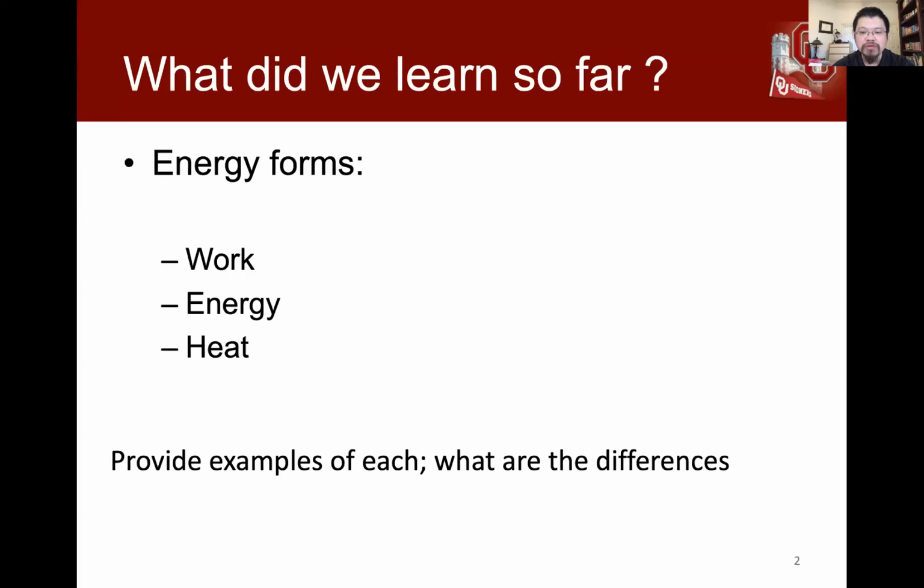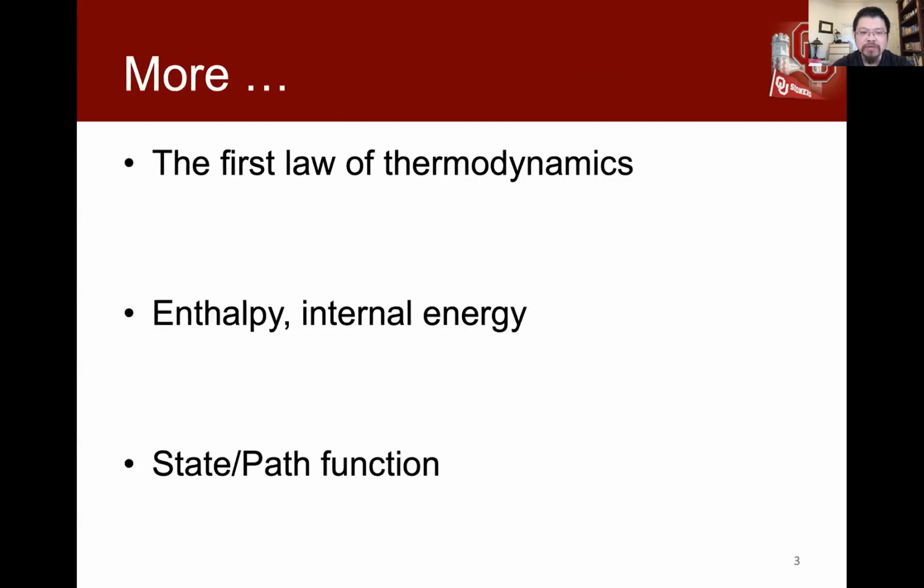That would be a violation of the second law of thermodynamics. We had a discussion on the second law to look at what is the maximum conversion from heat to work, which is determined by the Carnot cycle efficiency, right? So when we are trying to convert heat into work, we need at least two reservoirs at two temperatures, T high and T cold. That will determine the efficiency of the conversion. So that is the first thing I wanted to have a quick discussion on.